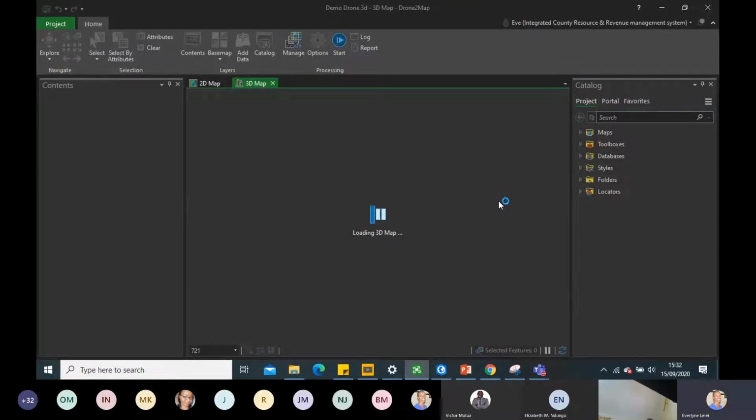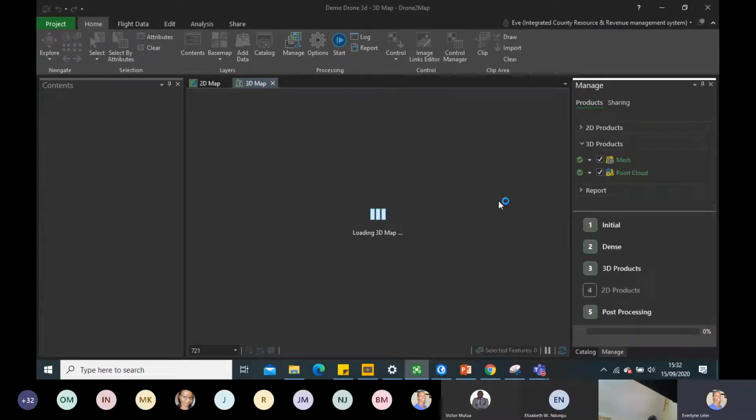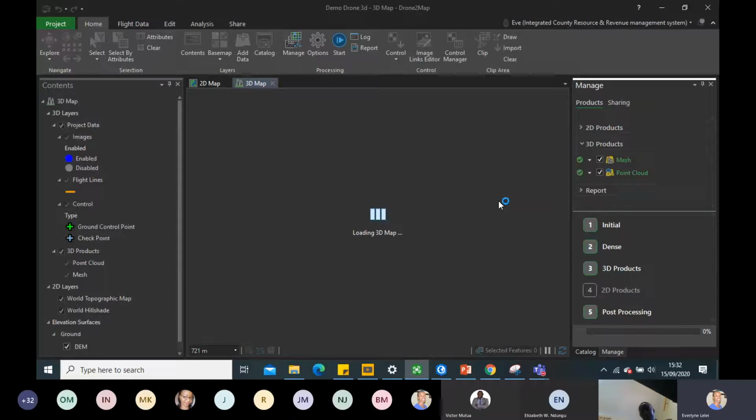So for these ones, these will mainly be scene layer packages, layers that you can publish to ArcGIS Online, and then from ArcGIS Online you can still add this to ArcGIS Pro if you need to do maybe analysis like visibility analysis. Then you can do any other 3D analysis with your data set.